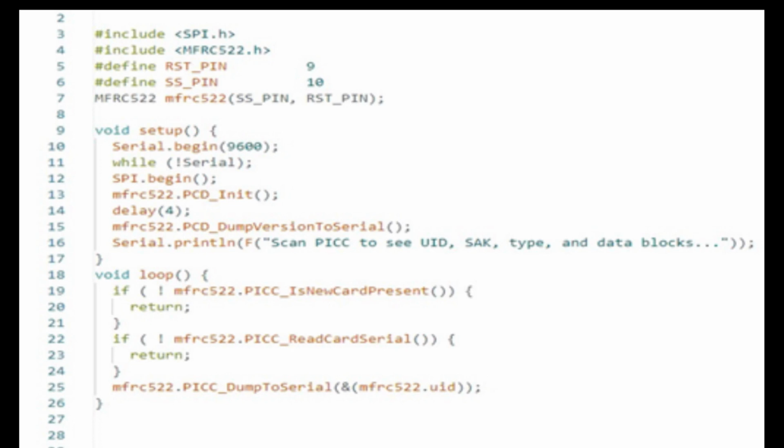It initializes serial communication at 2400 baud, RFID's language. In the loop, it listens for serial data, parsing it to extract the tag IDs. When a valid tag is read, it proudly announces the ID to the serial monitor.